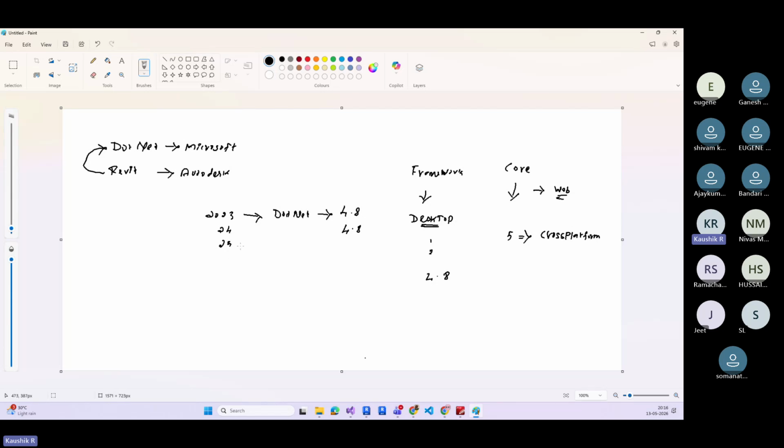So the .NET versions are 4.8, 5, 6, 7, 8, 9, 10. Up to Revit 2024, Autodesk used 4.8. Starting from 2025, they have converted their .NET version to 8. They skipped 5, 6, 7, and this is a very massive difference in their architecture. Now on LinkedIn everyone is speaking about how 25 and 26 have changed to .NET 10.